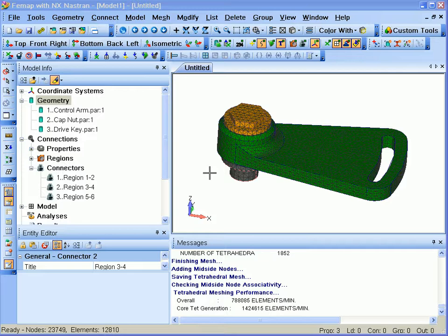the boundary conditions, the constraints, and the loads. Now, because we don't have load and constraint sets created, it's actually easier to use the toolbar because it'll prompt you for a load or constraint set. Or alternatively, you can always pre-create and have a template and have that automatically loaded when you start FEMAP that has a load and constraint set predefined in your new models.